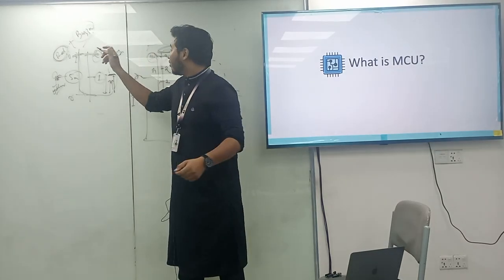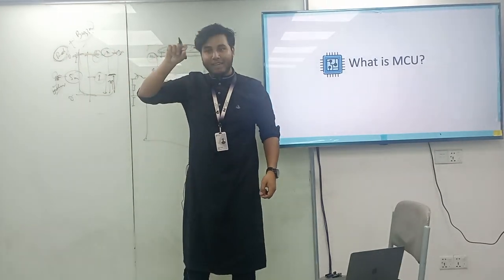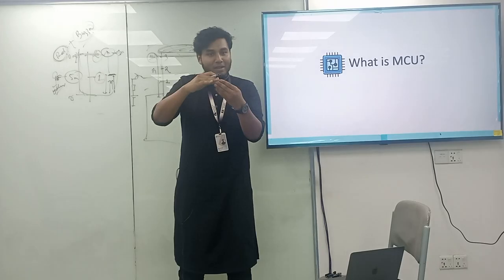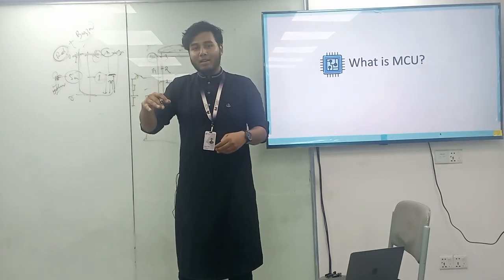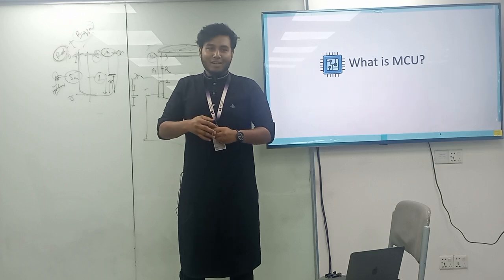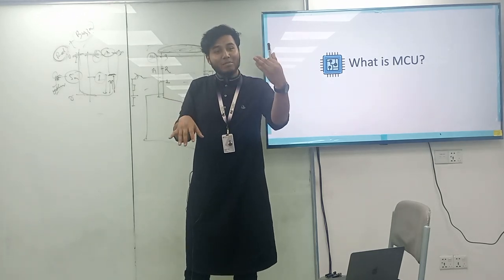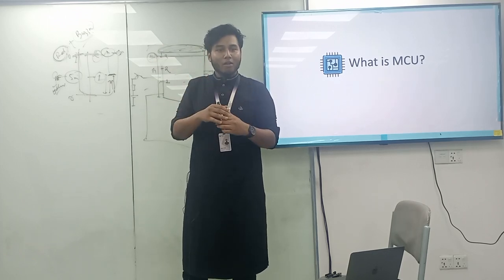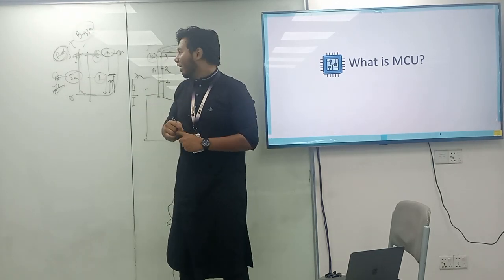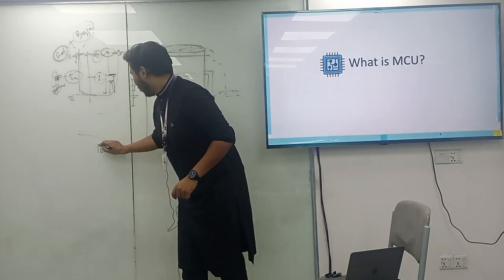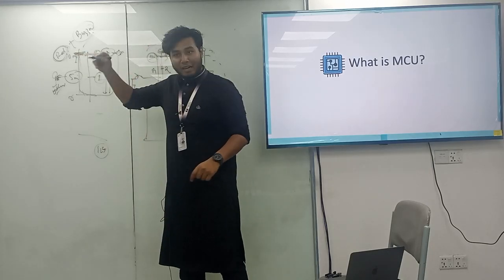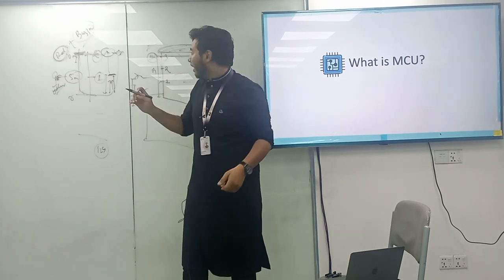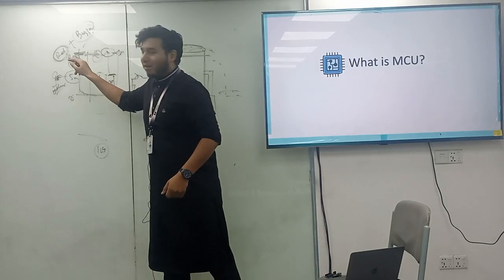So you are going to set that alarm, right? You are going to set that indicator in your own way. Are you going to set that alarm at 9 meters or 9.5 meters or exactly 10 meters? Exactly 10 meters? Or slightly less than that, because you are on the first floor. Whenever you set the level at 10 meters and the tank is full, what is the efficiency of your system? To make it more efficient, you have to put it at 9.5 meters. Do you get my point?